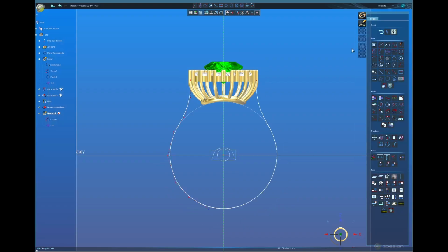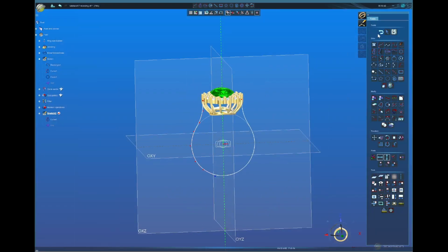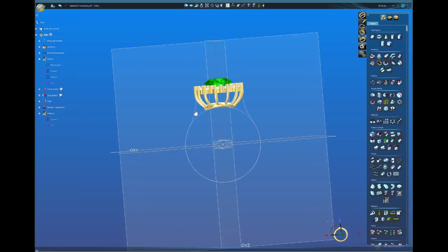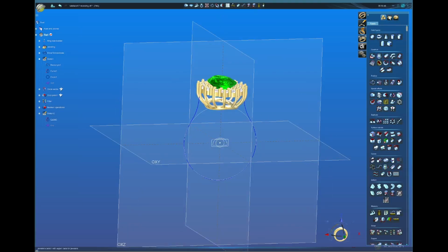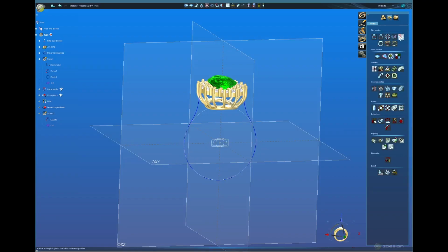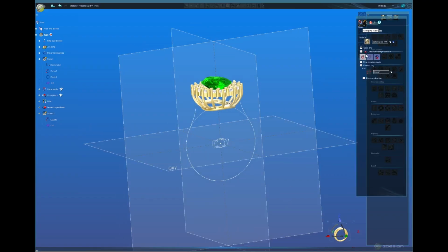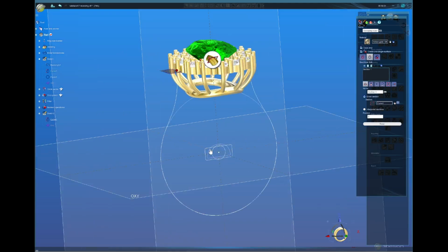We click OK, and now you're gonna run. Let's get out of here. We're gonna get this curve, and we're going to run with the sweeping wizard. We're gonna run create a single surface. Second tab, you're gonna get a section. It's the profile that we did here.